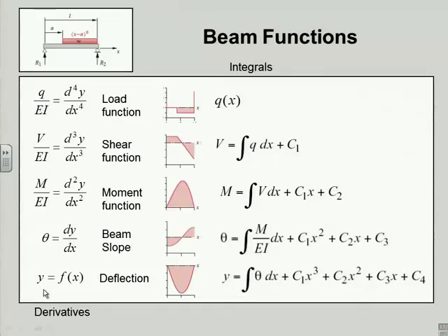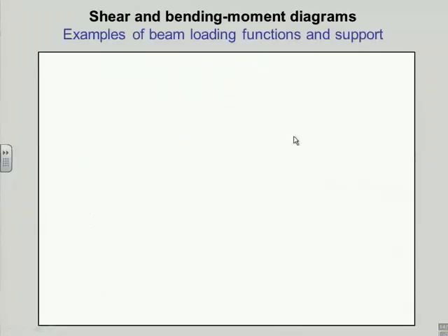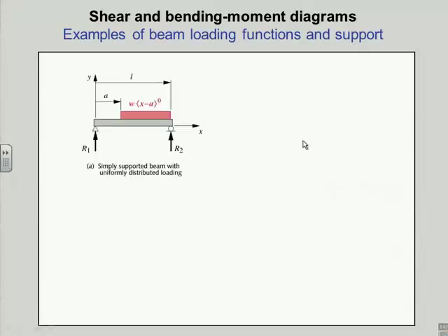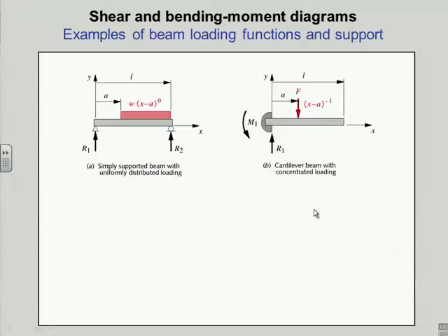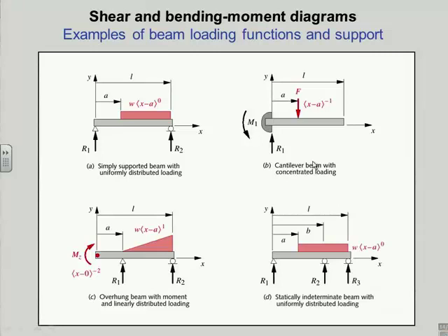Quite often you have a deflection limitation as opposed to a strength limitation. In other words, I'm not looking for the beam not to fail. I'm looking for it not to deflect more than X. Okay? And in most cases that will mean it's far from failure if X is small. I should say Y, because we're using Y for up and down. Okay? So I have to somehow manipulate these equations. So what we're going to do that is, well, I guess I haven't got to that slide yet.